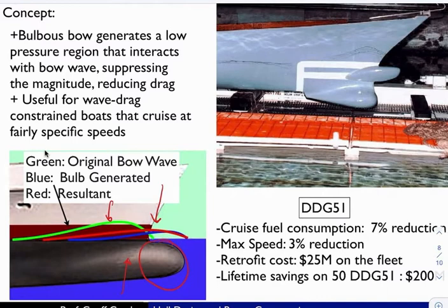Outside of that, they may be detrimental because now you've increased the surface area. Certainly at lower speeds, the wetted area is going to be up, which likely means the increase in viscous resistance that comes from the bulbous bow will probably outweigh the decrease in wave making. So if you play around with this in your project, you might find that you can make your situation worse or better by moving that bulb up or down in the water column. That's the HB term, or making it larger essentially in cross section, and that's the transverse area of the bulb.